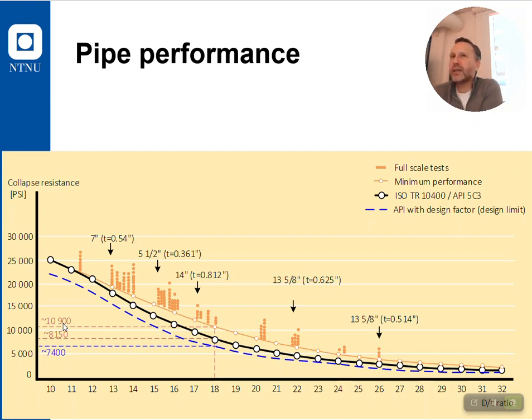So it's again a Volkswagen Beetle. It can take anything, and it makes sense what the industry is doing for some areas. For example, offshore fields where you drill from a platform, because if you get a little bit more casing wear than what you planned for, you need a little bit of extra leverage, a little bit of extra wall thickness. Yeah, go ahead. Is there any test like this, numbers on casing with recorded here?